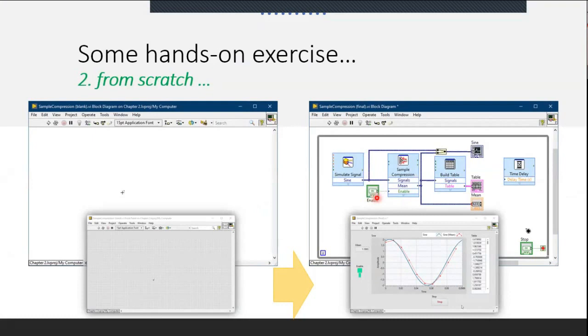When we disable it, there was no mean value in the graph. So that way we can control it. For example, I connect this enable/disable here, and it was controlling the data in the graph because this connection was done by this line and connected to this waveform. Until you connect these inputs and outputs by wire somehow, you cannot relate those controls and outputs.